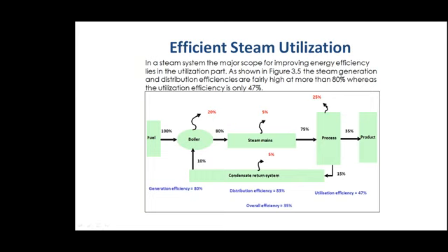As we said, heating up water in a vessel. In that process, what happens? The actual requirement, to heat the product from 30 to 90, the energy requirement is only 35% of the total fuel content. So 35% of the energy contained in the fuel only is required for heating up the product.